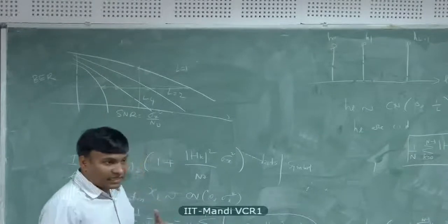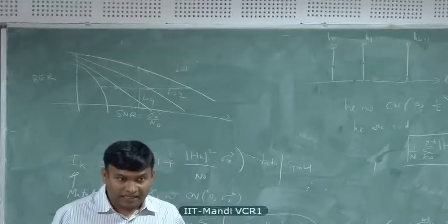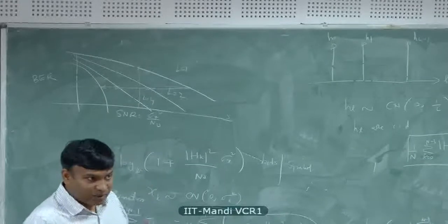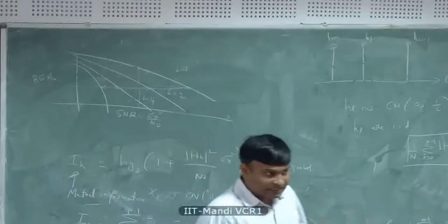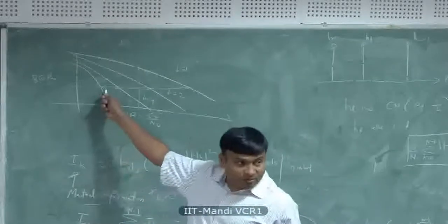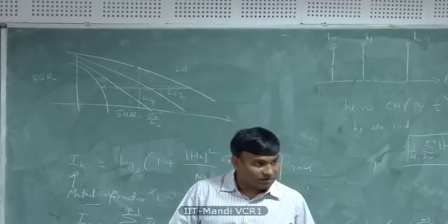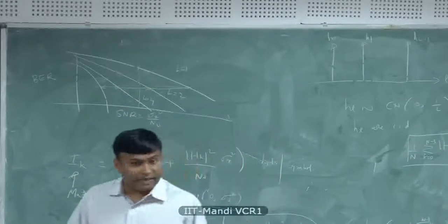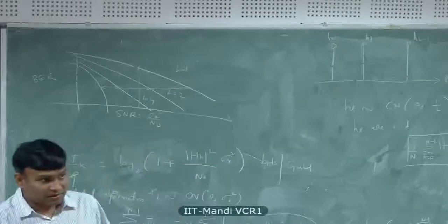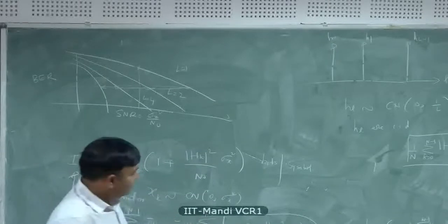So if you design a transmission and reception, or an encoder and decoder, cleverly, if you can tap into this diversity that is already available in the channel, you can get close to the AWGN case, that is, no fading scenario. You can, with a 1 or 2 dB penalty. It's possible, because the channel has plenty of diversity.